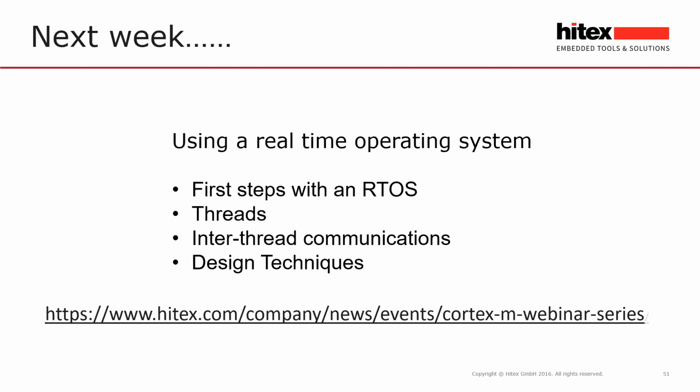I would say it is worth investing the time in experimenting with an RTOS. Once you get familiar with it, it provides you a development framework that you get very used to, that helps you build reusable, easily maintained code. And once you've invested the time to learn about it, you really won't want to go back to using pure bare metal code.